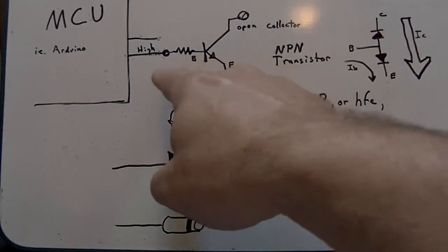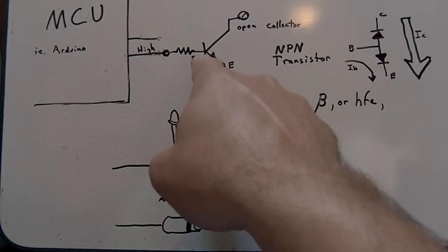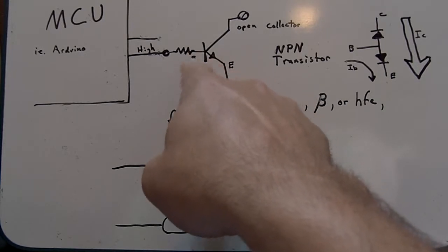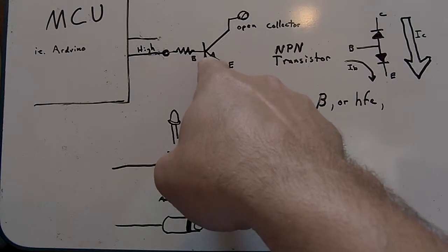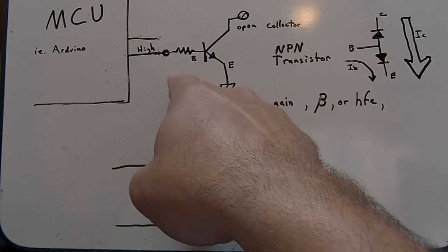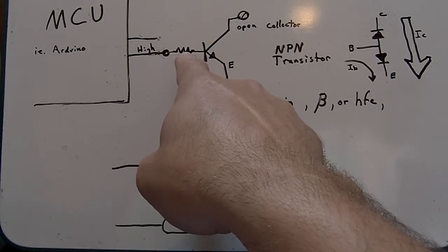I would do the resistor the same way in my last example. I'd take this 0.6 volts off of my 5. So I got 5 volts minus 0.6, so now I'm down to 4.4 volts. 4.4 volts divided by 20 milliamps, let's say, would give me that resistor.